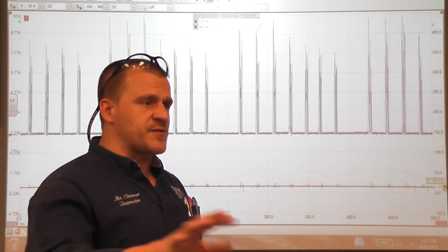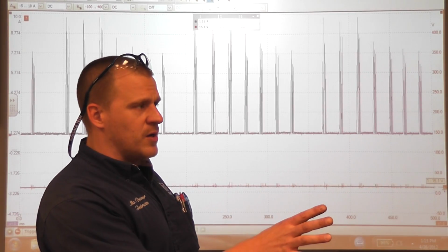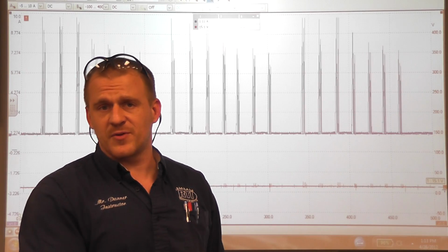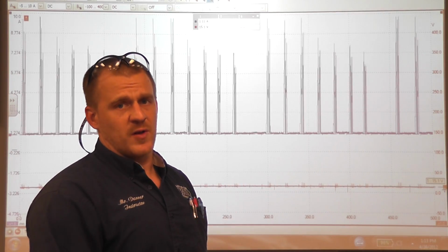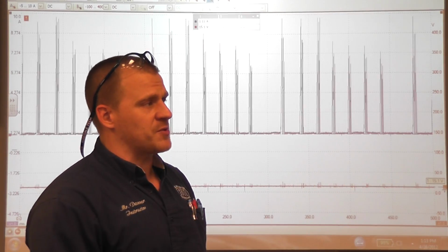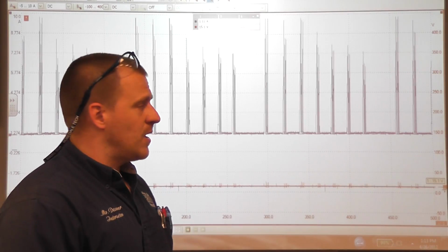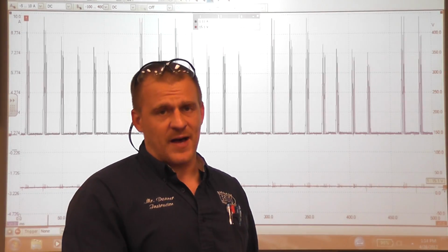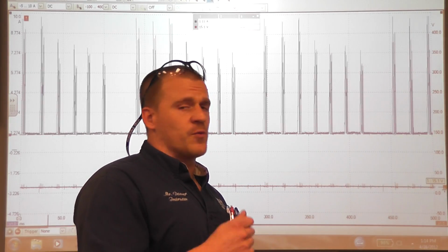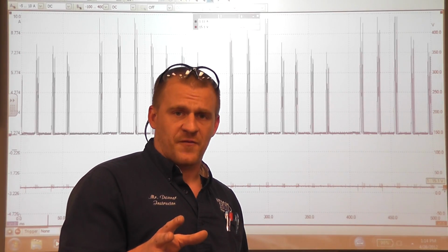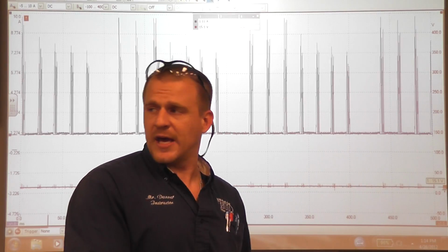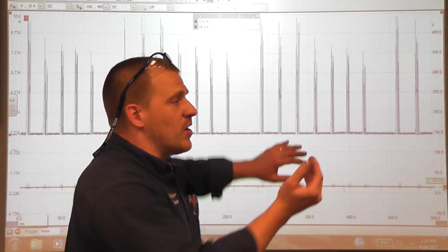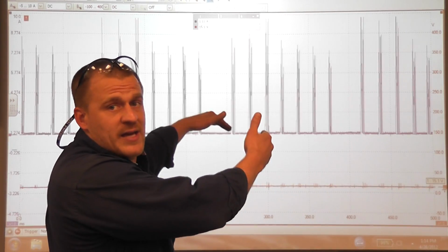My focus for this video is not to show you that part, but if you started with a fuel injector on the number 6, boy, would that throw you for a loop, because the computer will shut the injectors down to protect the cat. So you have to be careful with that. One of the keys to identifying that, though, is when you shut the car off and restart it, that injector will fire for a few seconds before it shuts down again. And then you can see that it's an intentional shutdown. In our case here, that's not the case.